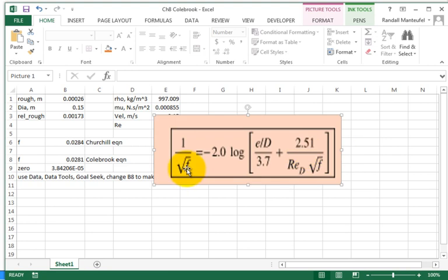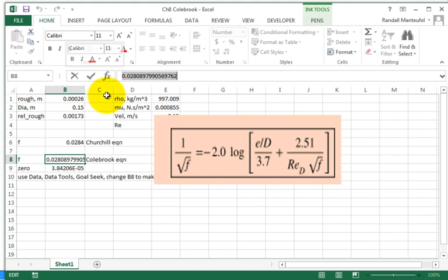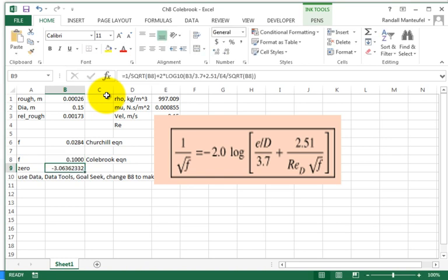But you have the friction factor here, square root, and you have the relative roughness, and that's log base 10. So what I do in Excel is I say, I'm going to guess the friction factor. Maybe this one to start with is 0.1. If I put it into the Colebrook equation for that Reynolds number and that relative roughness, the right side is not equal to the left side.